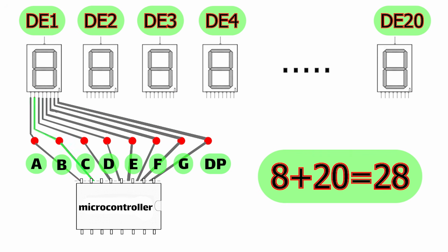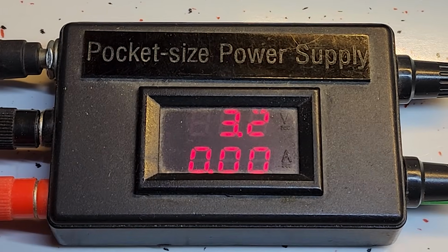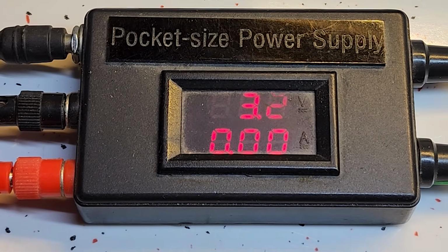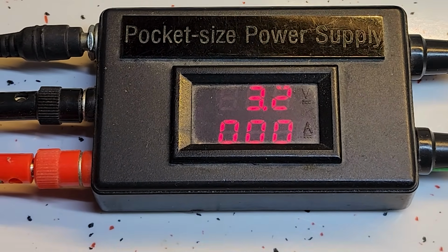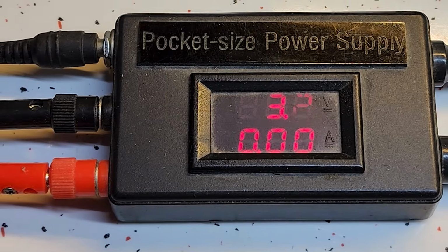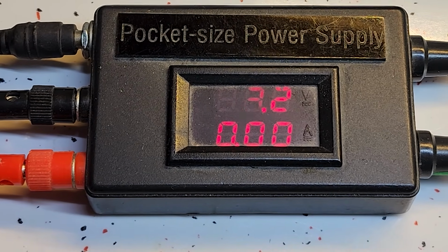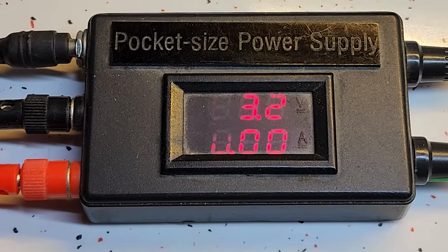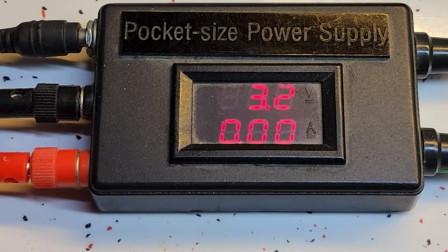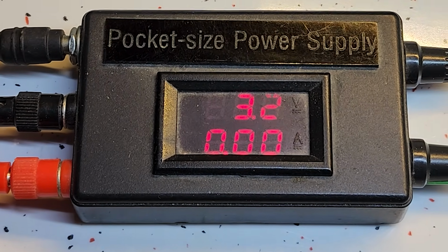Another problem is that the LEDs are still connected directly to the microcontroller pins, and the power needed to light up the LEDs must be supplied by the microcontroller. Furthermore, the microcontroller has to dedicate a large part of its processing power to changing the pattern from one digit to another. Another drawback is that while the multiplexing method creates a visual illusion for the human eye, making them see the digits as constant on the display, the digits created with the multiplexing method reveal their flaws during video recording and photography. When filming, this updating of the segments is clearly visible.